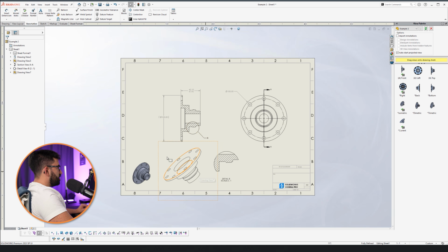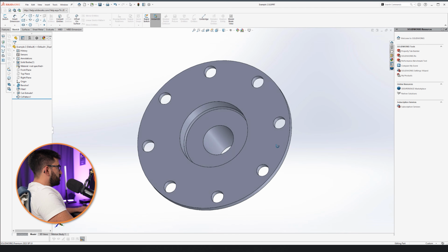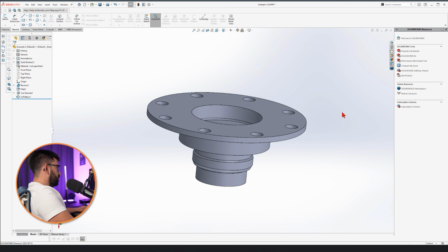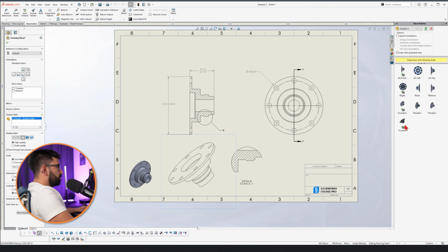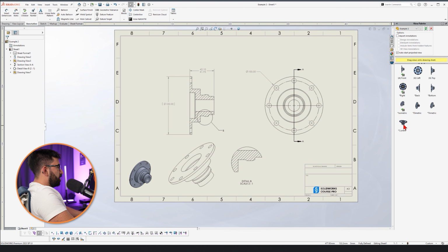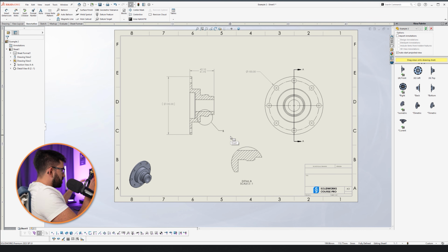If you have a component that is a little bit odd in geometry and you want to show it at a certain angle, you could work with the current view: go back to the part mode, change your current view, and let's just make it something odd. Rebuild, go back, and rebuild again. This will change. Didn't. Now it changed. Okay, took a while. I was surprised why it's not changing, but this is the new current view. So this is also useful to know. Sometimes it also surprises me. Be patient. Just press Control B or Control Q on your keyboard to rebuild it. It refreshes everything and syncs the part mode and the drawing mode together.